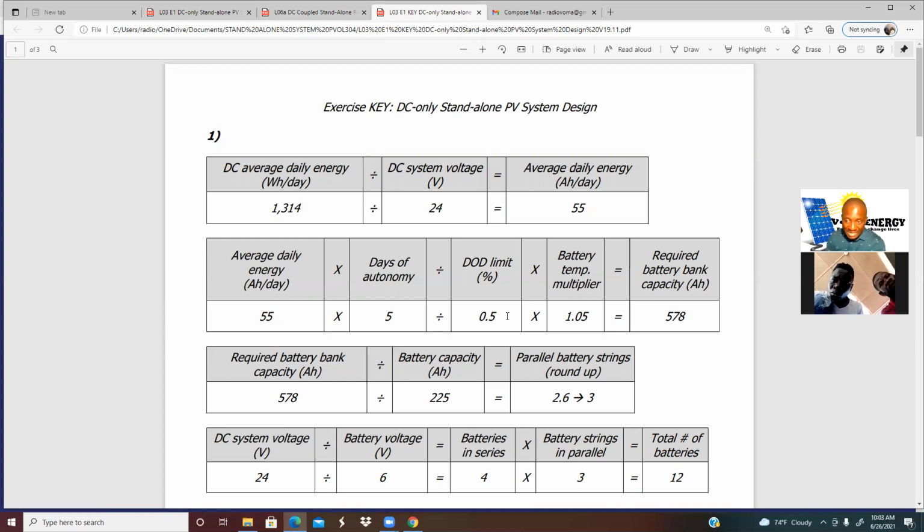If you make a mistake and you don't set a depth of discharge, this person runs the battery, it's not a lithium ion battery, all the way down to the ground. Now the battery can never take charge again. They have spent thousands of dollars to buy a battery bank that can't take charge. And you're going to be in a big mess.